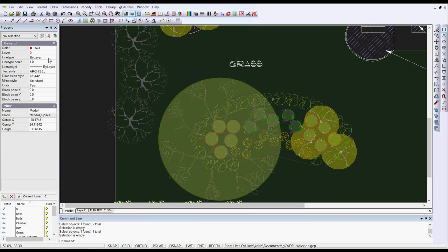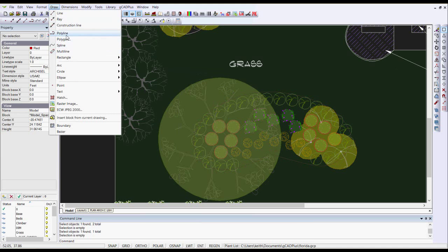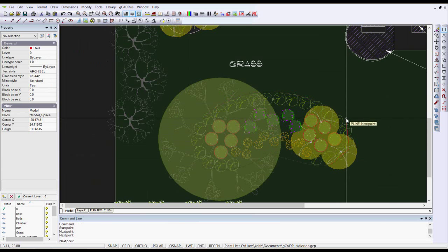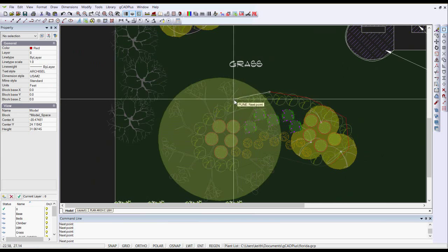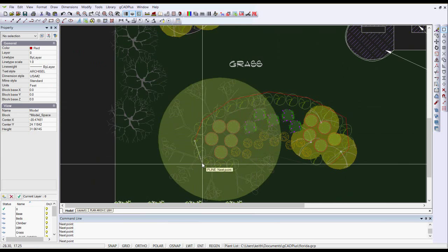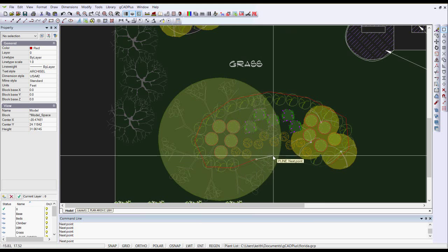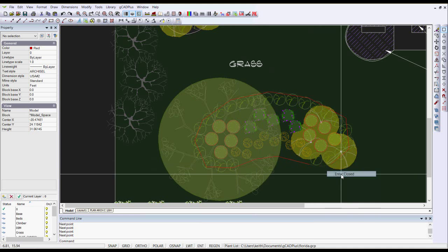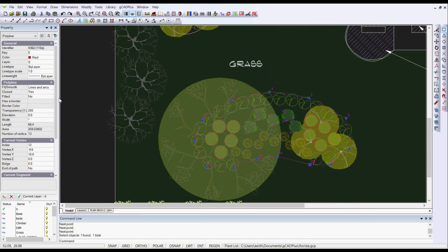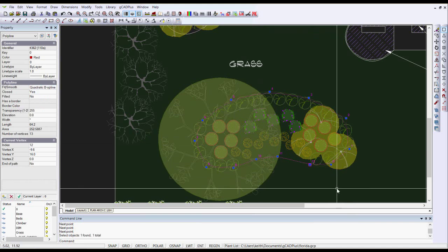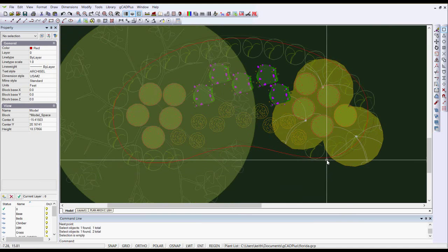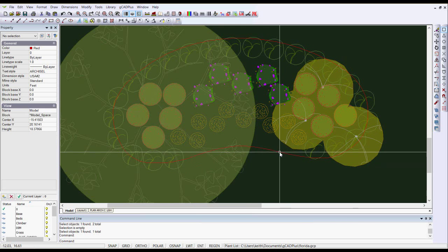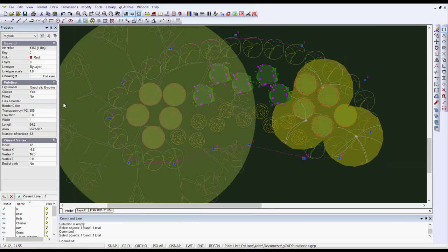I'll unselect all. My drawing color is red. I'll draw a new polyline, and I'll just set some vertices. I'll do it crudely to show you what I mean. I'm just setting some vertices now to make a kidney shape, and at this point here I'll say enter closed. Then I can select that polyline and apply quadratic fitting to it, so I get the sort of shape that I want without that awkward combination of vertices. So there we now have it, and we could certainly fill it.